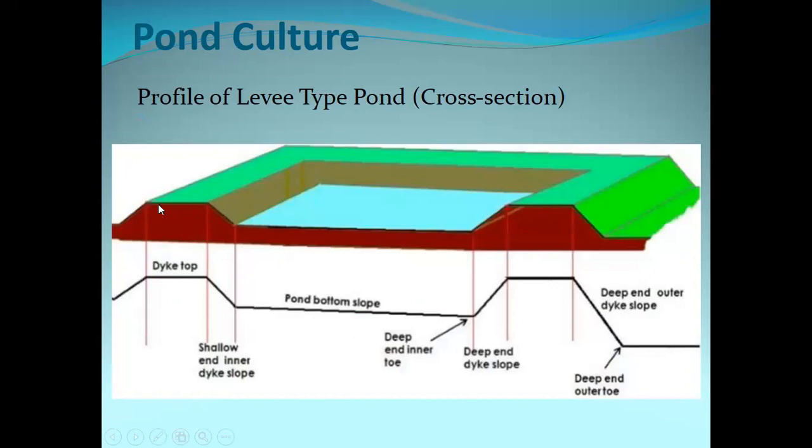This allows for structural integrity of the walls. Imagine it becomes very steep, and the top is not suitably wide enough. It could fall apart very easily, and you can't really move about on top of it. That is why there is a certain slope to width ratio for your levee or your dike.